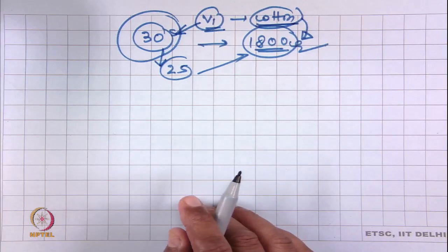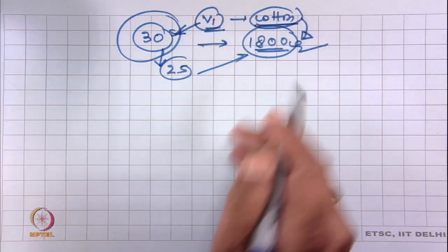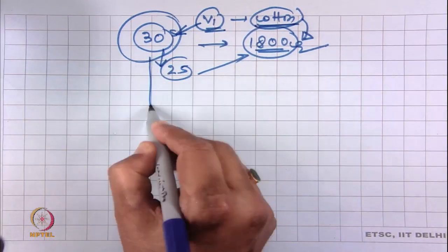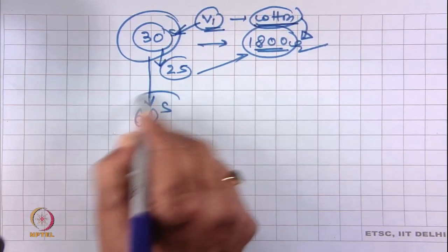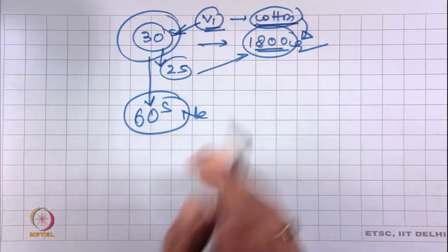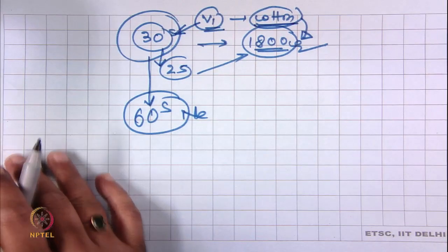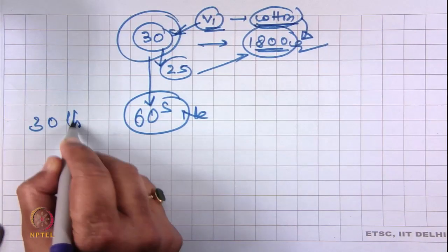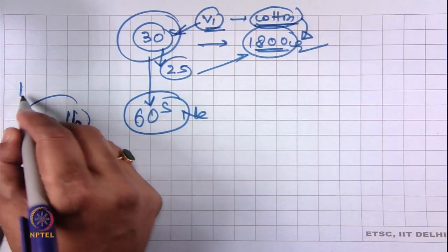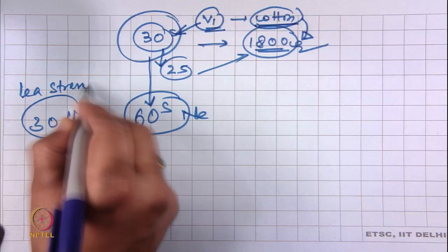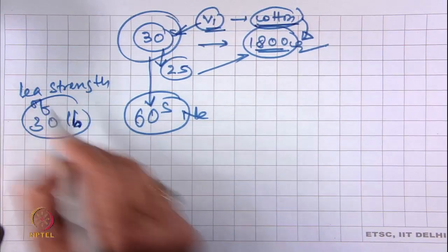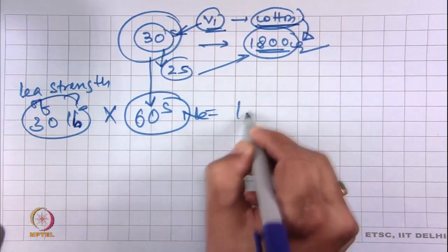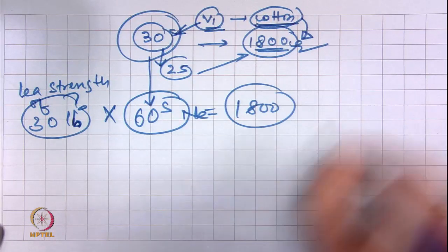CSP? No. Suppose with this variety, 30s count, it is a medium variety cotton. Now, if we try to produce yarn of 60s, any very fine count, will it give us a strength of at least 30 pound, so that we can get 1800 CSP? No,